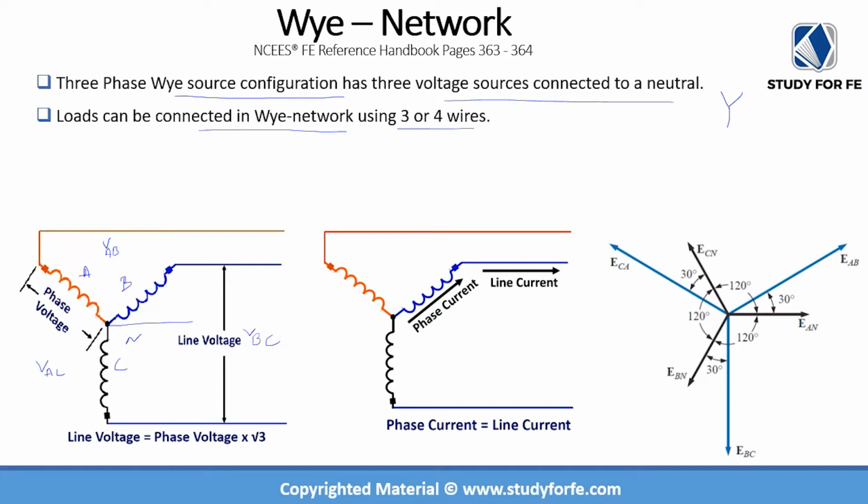So depending on where exactly you are in the power system network, you may or may not want to bring out the neutral, and it also depends on what type of grounding you are doing. If you're doing resistance grounding, then neutral is typically not brought out. If you have a solidly grounded system at low voltage, then typically neutral is brought out. But more and more, the preference, it seems, is that neutral is derived as close to the loads as possible.